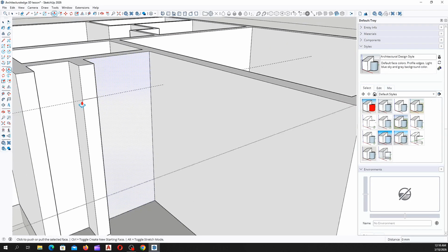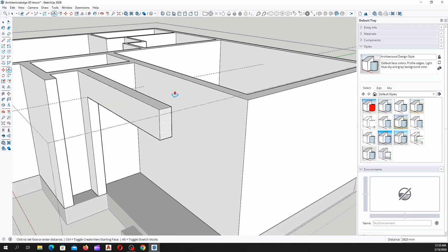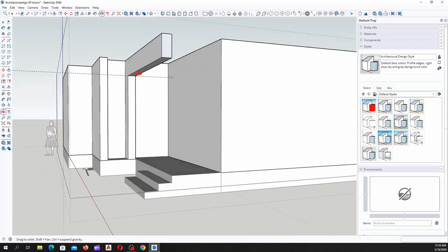Okay, then you use your push tool, you push to this point. Once you are pulling out, you snap to this point. From our introductory video to SketchUp, I taught us about inferencing. So you see, snapping to this point is called inferencing. So now I'm picking a reference from that point to extend our veranda beam. So this is our veranda beam now. So I snap it here. So we have this at this point.